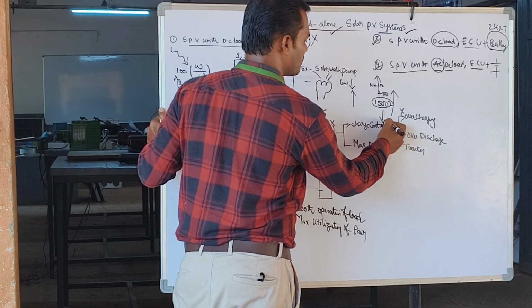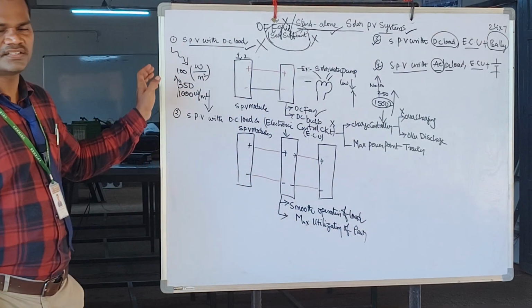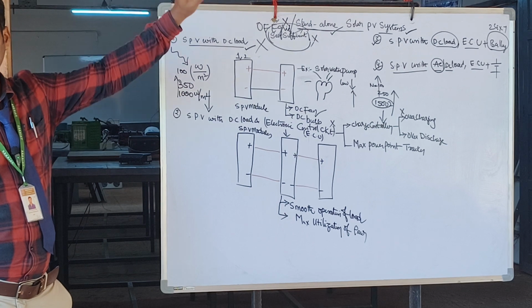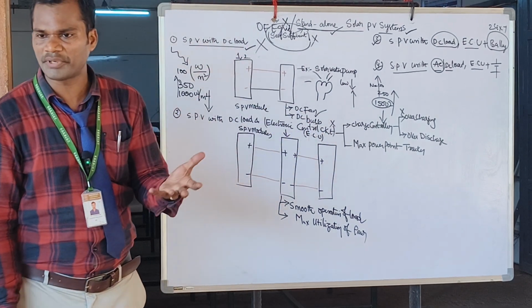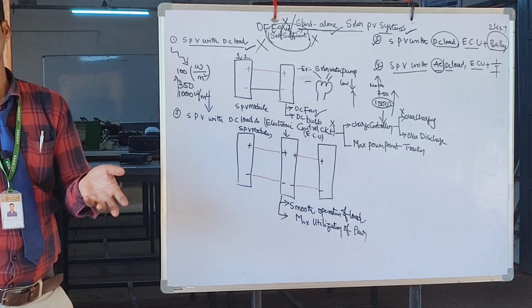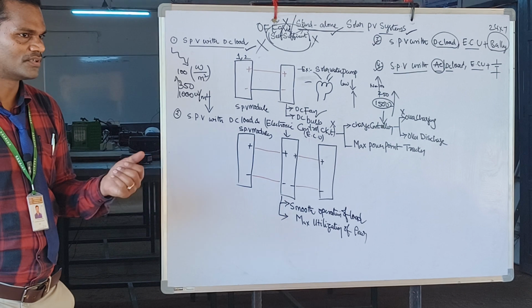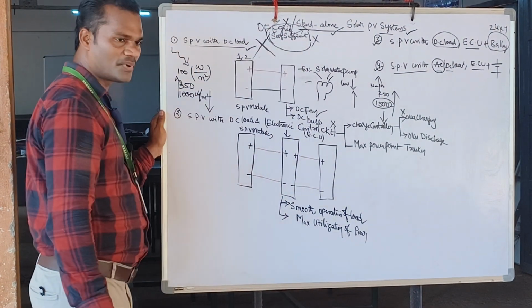In the evening the same will happen. Again the fan speed will decrease, because the solar radiation is going to decrease. Is it a happy load? I mean, can you say that the customer having a DC fan and a DC bulb will be happy? The bulb is continuously flickering and the fan is continuously changing its speed. Is it a desirable output? No. That's why I cannot say that this is a proper design. This is an improper design.